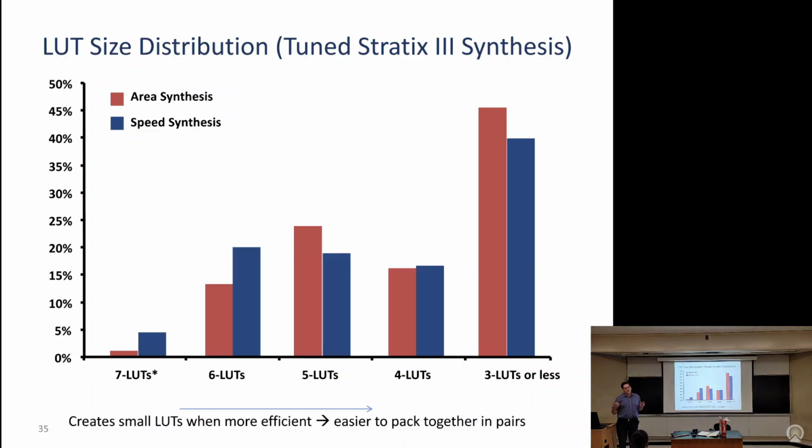But your problem is that the routing failure rates get really high because you've made the routing problem much harder. Instead of saying get to this logic block, you're saying get these signals to these specific wires. When we talk about routing architecture, I'll show you that's actually a much harder problem because we've essentially cut away some stages of flexibility. So yeah, academics have looked at this in various ways.